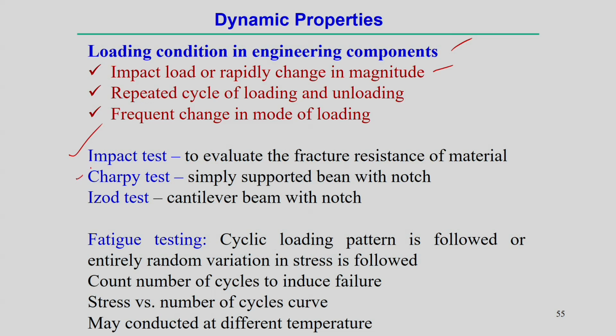There are two standard test methodologies, the Charpy test and the Izod test. In the Charpy test, we use a simply supported beam of that material, and we make a notch to ensure the fracture happens at the notch. And in the Izod test, a similar kind of material is made in the form of a cantilever beam along with a notch. Both are impact testing methodologies.